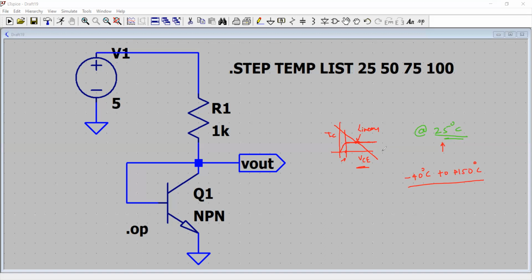Same goes for voltage reference. When you design a voltage reference, you want it to be constant irrespective of variations in the load, variations in the supply, etc. So the purpose here is to demonstrate this. Let's say I am generating a reference voltage V out. This can be one of the voltages to another block. For example, I will use an operational amplifier here, and this voltage reference comes here. So here is my circuit, and here comes the reference. I want this to be constant. If there is a variation in the temperature, it should still remain constant, right? So now let's see what I'm doing here.